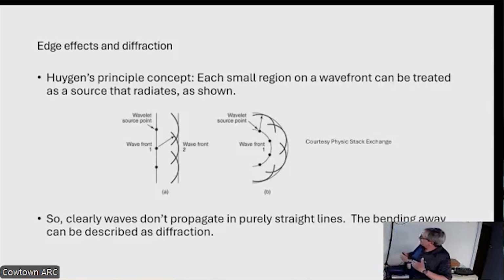And so we're wanting to see what's the distance, how far do I need to go before I see an antenna pattern that's going to stay the same. It's not going to change the pattern itself. Clearly, the energy will decay, right, as we propagate outward, but the pattern will stay pretty much the same. And so that's where we have different field regions associated with antenna radiation.